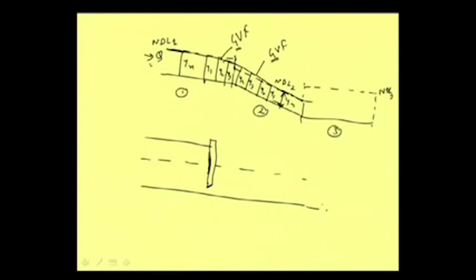and from the main river, suppose at high flood period water enters into the tributary, we want to avoid that. So, we are putting a sluice gate here, so that when the main channel water rises, then we are closing this and the water cannot come into the sub channel.